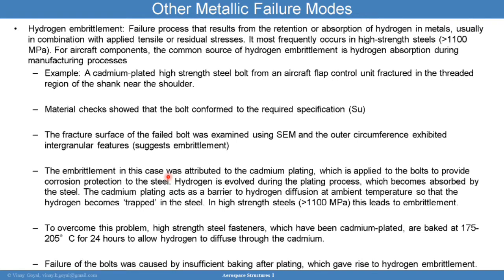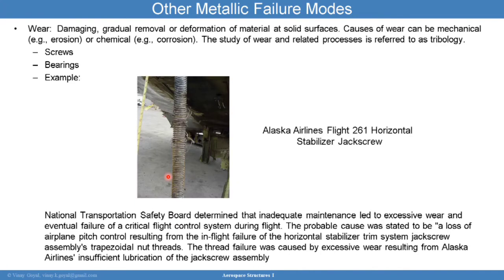And so in essence, the root cause is very simple. Failure of the bolts was caused by insufficient baking after plating, which then led to the hydrogen being trapped, which then combined with the high tensile loadings that you could have to produce cracking that then got accelerated due to the hydrogen embrittlement process.